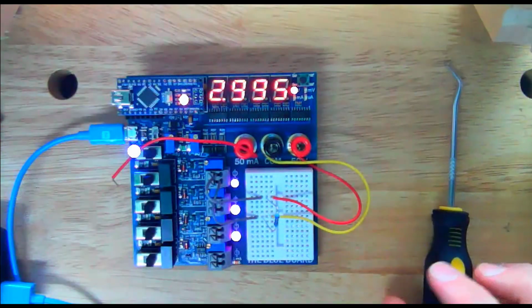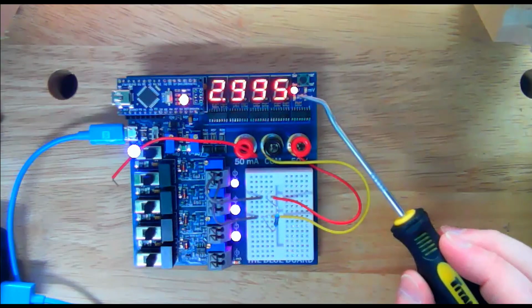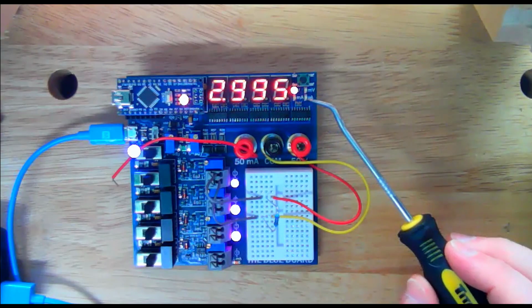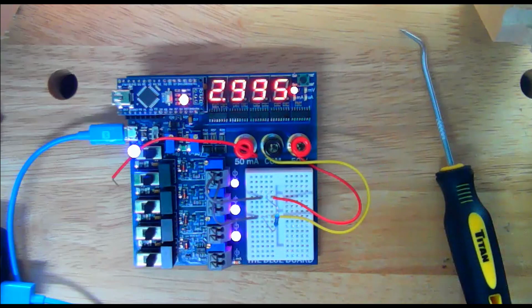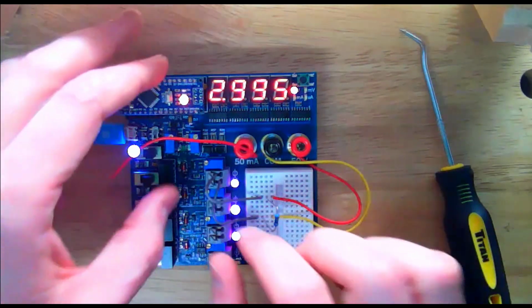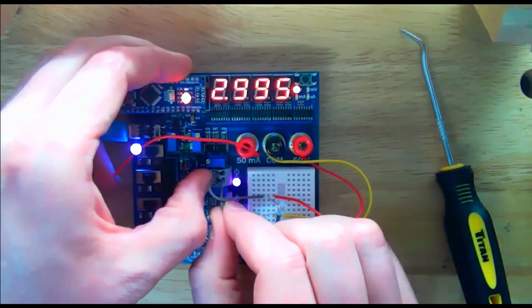Okay, 2.99, we're back up to 2.995 volts. So we have volts, millivolts, milliamps, microamps of current. Let's say we want to get a 10 volt supply. Well, we don't have a 10 volt supply. We have a 7 and a 3 though, and these are isolated supplies, so we can connect them together. So if I want to create effectively a 10 volt supply, I can,